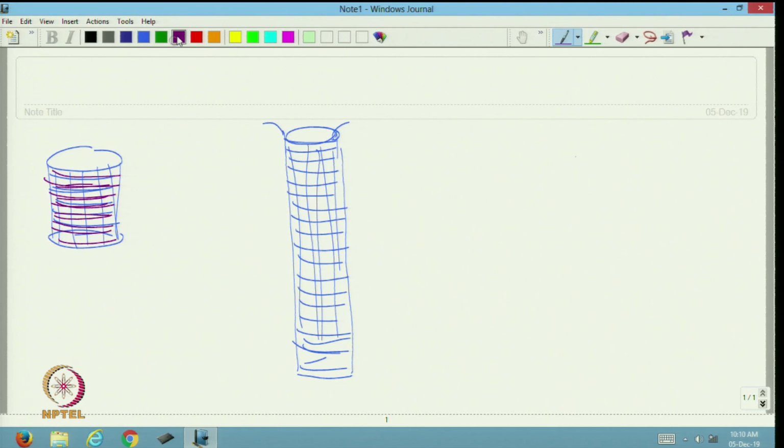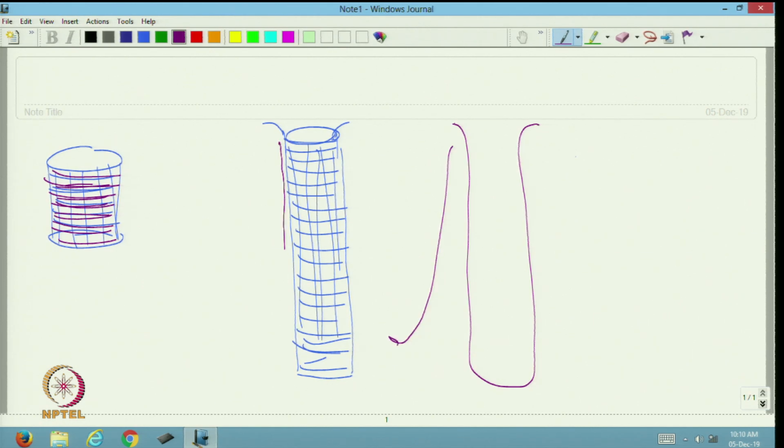And the prefabricated filter bags are used. These bags are taken here and just placed over this. These are hanging. This is a bag filter. Okay. This frame is only for support of the bag, and the frame is required, otherwise the filtration process is not possible.